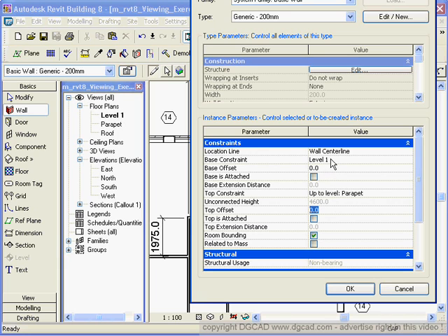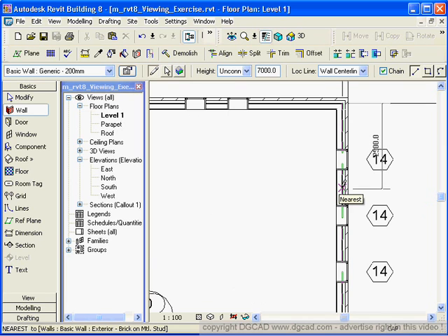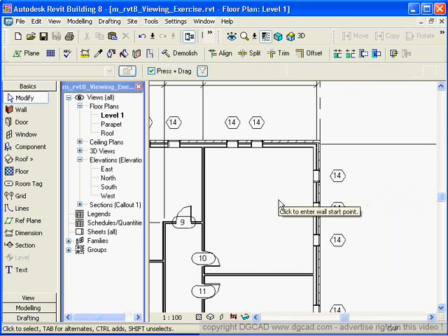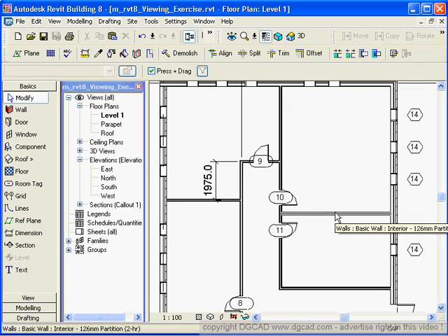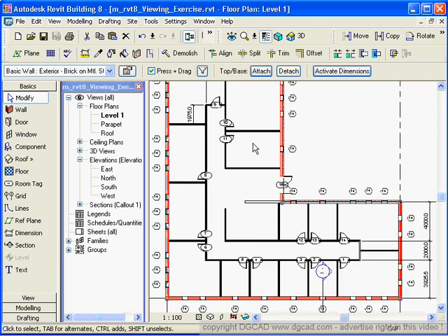So the main thing there with our walls is the top and bottom constraint as I place the wall, and as you near a point, again, you can tab your way through. If you want to select a bunch of walls in a chain, you can hit tab. Oh, that one didn't work. You pick an outside one, hit tab, and it'll chain pick them all.